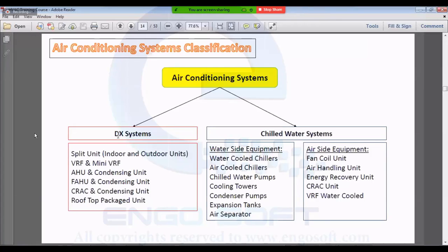So the total fresh air in the space is 30 liters per second, which is enough for the space, while the cooling load is small because we cool 70% of the air from 24 degrees Celsius, not from 46.